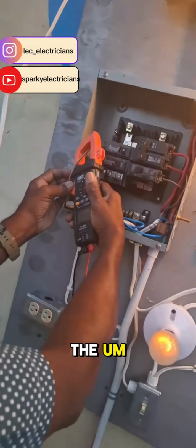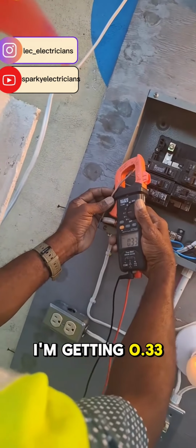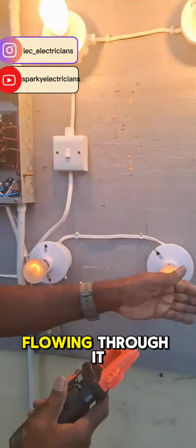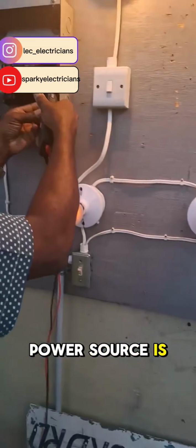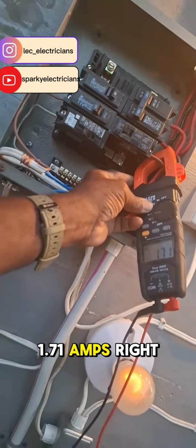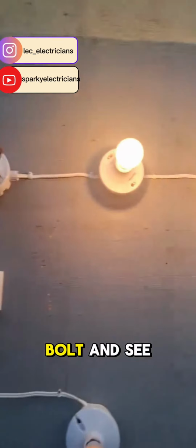So where the series current is concerned, I'm getting 0.33 amps, right? Just 0.33 amps flowing to it. And where the parallel circuit is concerned, I am getting 1.71 amps, right? So it's much more. I'm going to unscrew one of the bulbs and see if the current drops.